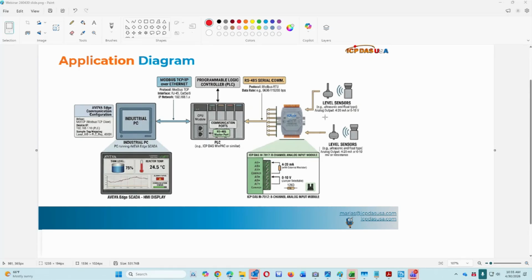So basically there was a remote data acquisition module here, which brought in the values from the sensor. It communicates the signal via Modbus RTU over RS-485 to the PLC, which is doing the ultimate local control. Now, using Modbus TCP to connect to this PLC, you can read data from the sensor level and control level, and you can also interact with the PLC, maybe for supervisory control, maybe for data logging, or for remote monitoring.